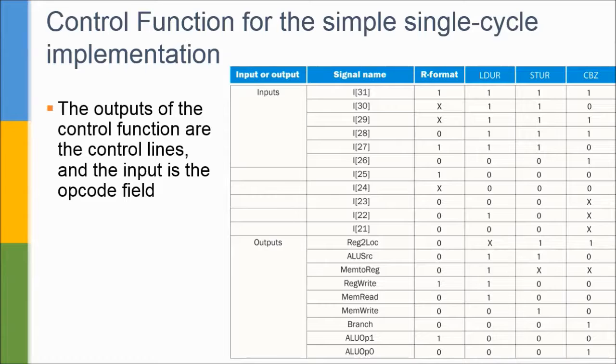Thus, the output RegWrite is asserted for two different combinations of inputs. We simplify the truth table by using don't cares in the input portion to combine the four R format instructions together in one column. We would otherwise have replaced that single column with 4 columns for the instructions add, sub, AND, and OR. The output would have been the same for all 4 of these R format instructions.